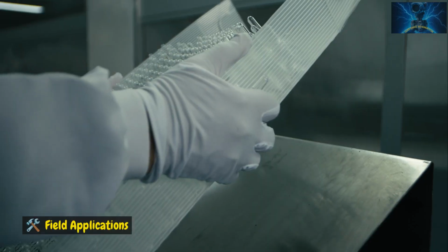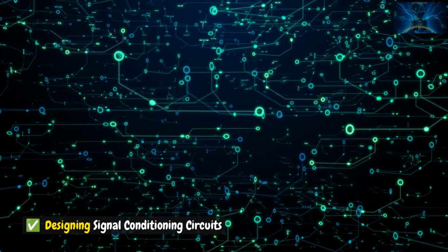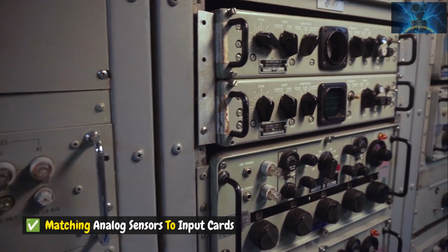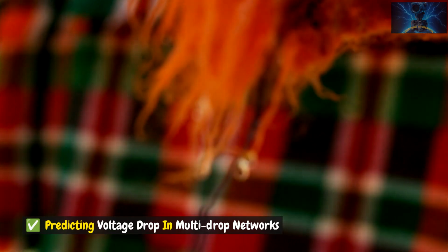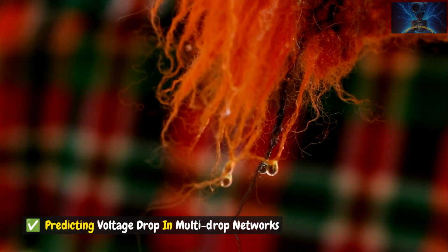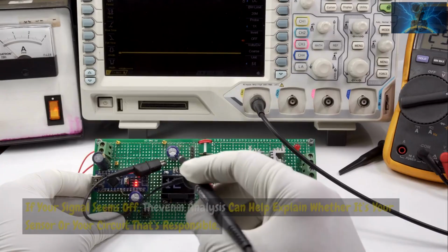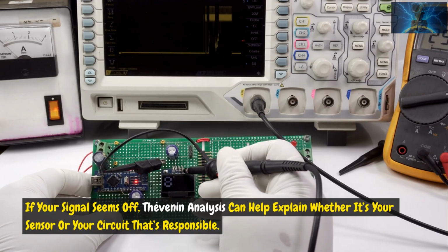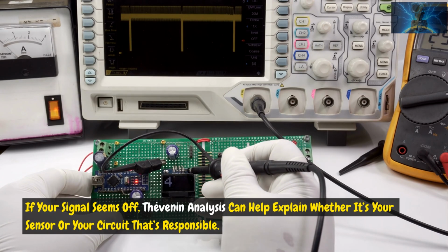Field applications. Designing signal conditioning circuits. Matching analog sensors to input cards. Evaluating input loading on op-amp circuits. Predicting voltage drop in multi-drop networks. Simulating unknown loads in circuit testing. If your signal seems off, Thévenin analysis can help explain whether it's your sensor or your circuit that's responsible.